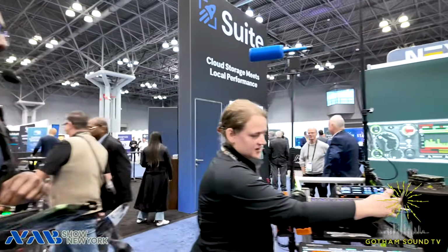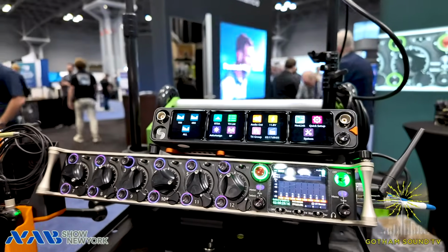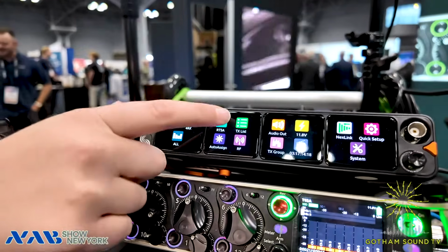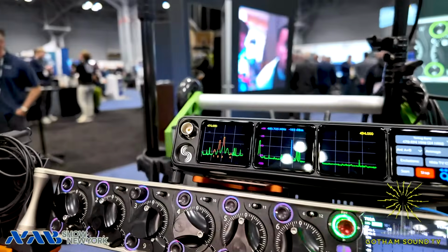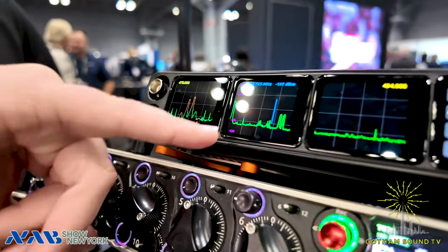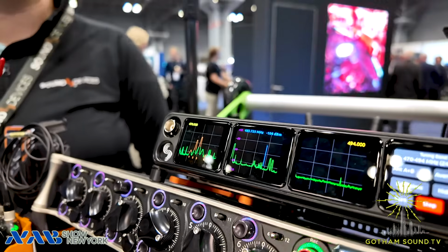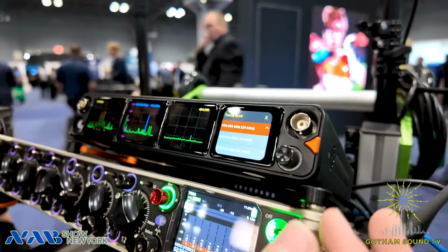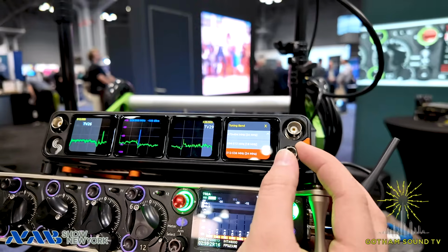So if we go into the menu here, I'll just show a bunch right on this receiver since we're standing right next to it. This is our front panel menu option. You can see I've got all these app-like features to let me know what menu I'm jumping into. Built into all of our Astral receivers, we have this RTSA right in the product. That's giving me a live view of the floor we're working on right now. The things highlighted in orange, these are my carriers. Those green little bumps, those are carriers of other people that happen to be in this room. So if I want to check out what's going on, I can change the tuning band, and as I scroll through the bands, you can see live what environment we're seeing in this room.